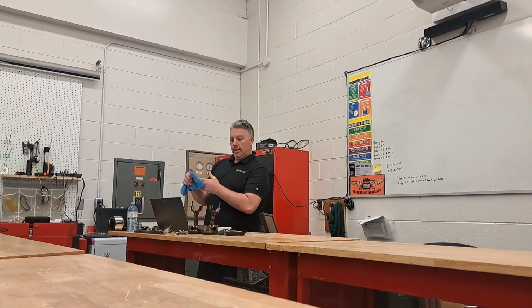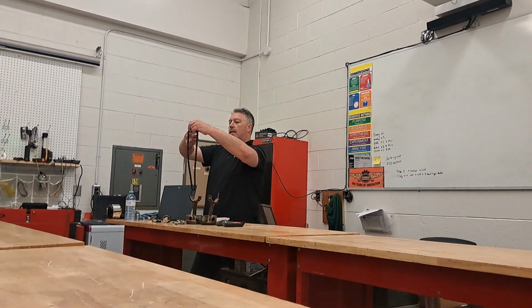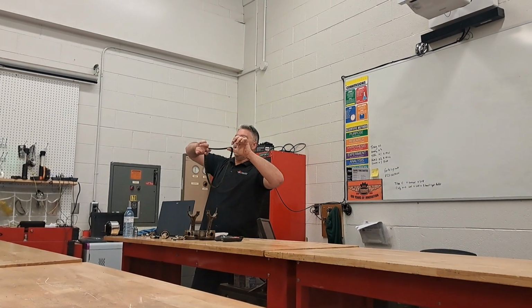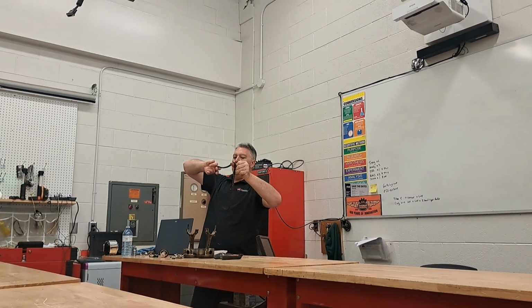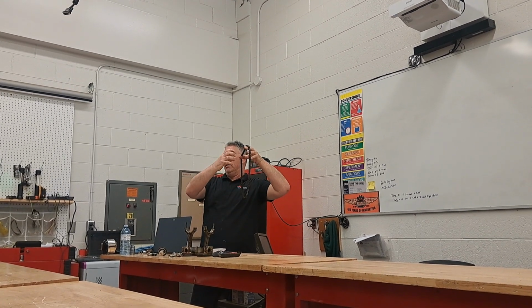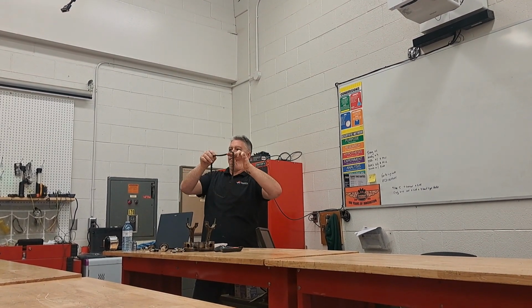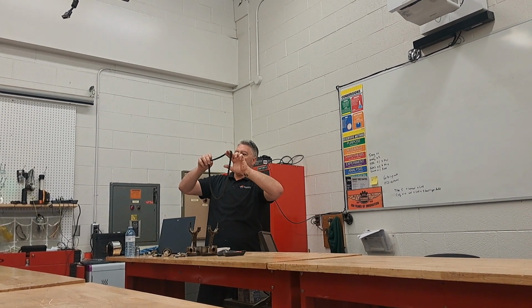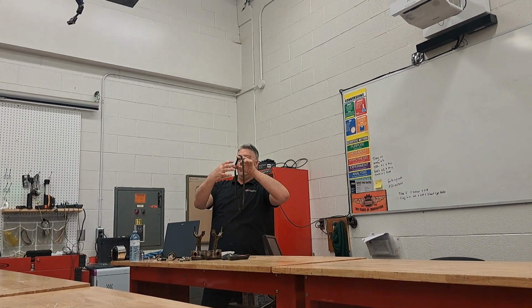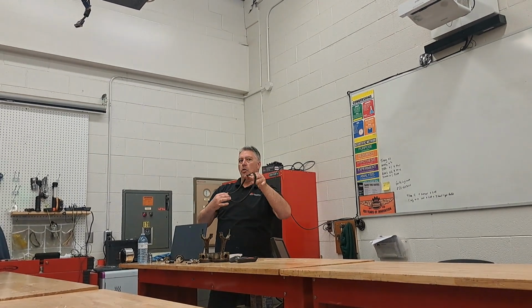What else was I going to say? Yeah, this is a timing chain. This connects the crankshaft to what? Any ideas? What opens up the valves with the lobes? Camshaft. So this connects the camshaft to the crankshaft. The crankshaft spins, and the camshaft turns, with perfect timing so that the valves open at the right time.